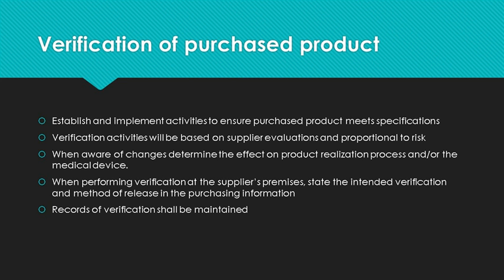When the supplier informs you they're making a change as per their written supplier quality agreement, it is your organization's responsibility to determine the effect, if any, on your product and process. So if your supplier is switching to a different steel mill, you would want sample product for chemical composition testing and to make sure new product reacts the same in your dies as the old product.